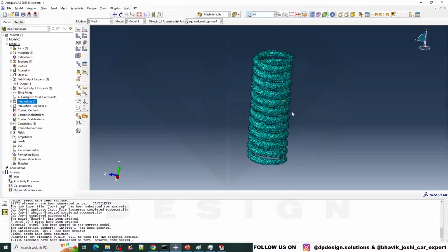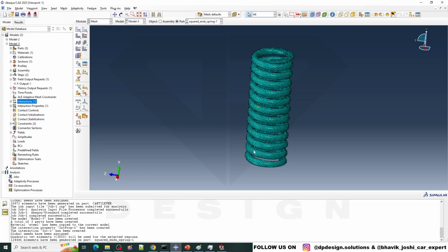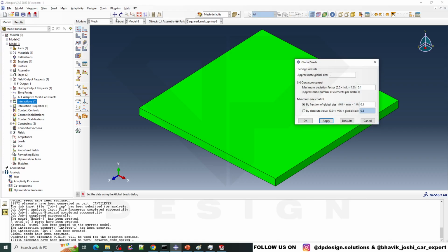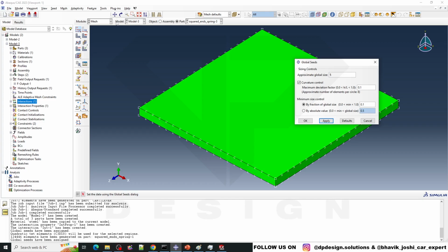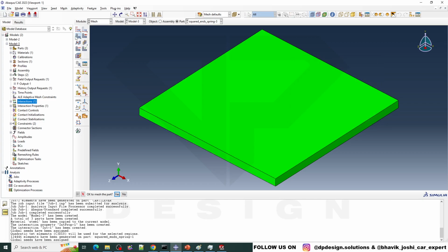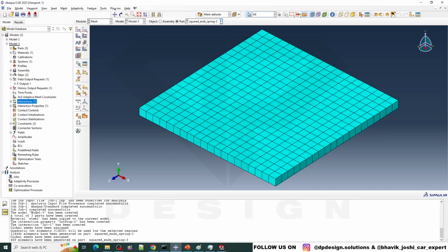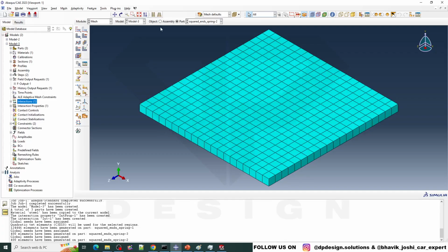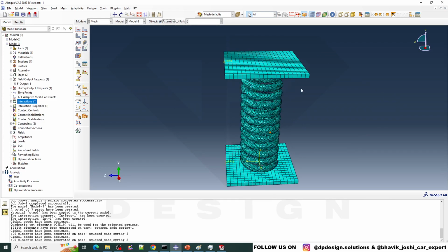As you can see, for fine meshing you can apply a lesser element size, or you can use HyperMesh. Okay, for three different parts, as it is an independent mesh, we have to apply it separately. Even if you apply a smaller element size here, there will be no effect because it is a rigid part. So you can create it as it is. Now go to the assembly. My total part has been meshed.